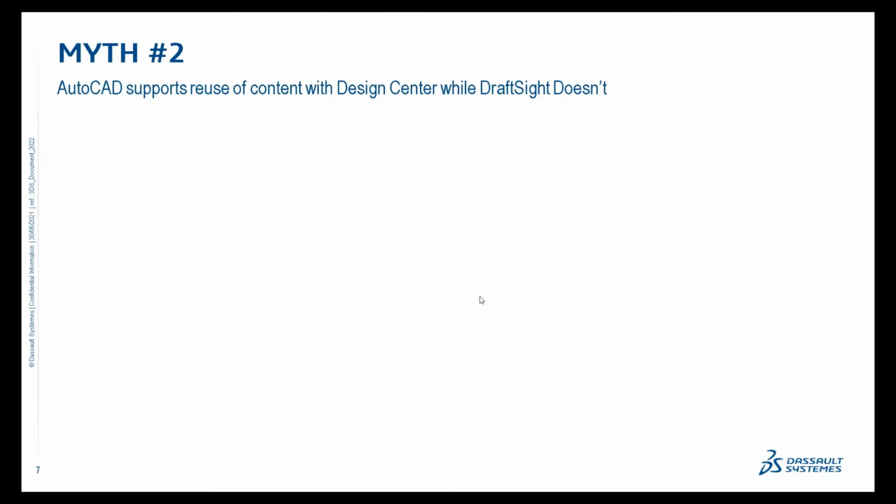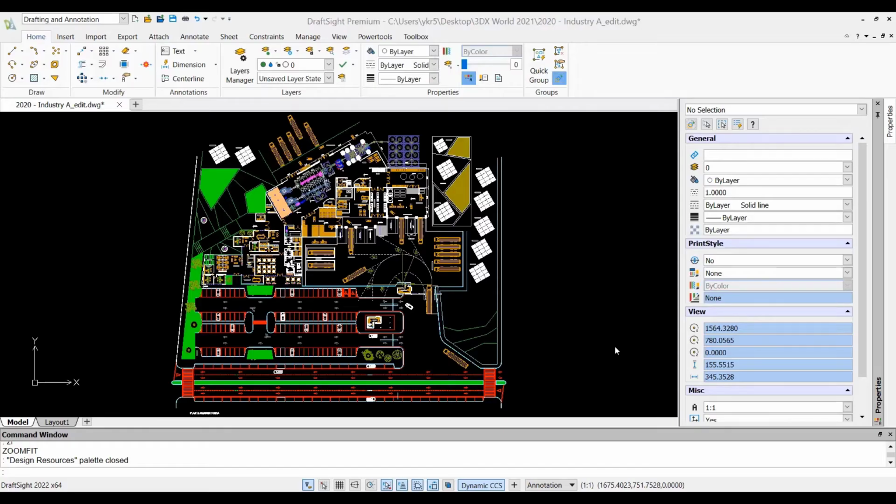Many people I speak with have not used or forget the power behind design resources. So, design resource can be used to capture objects from template and drawing files and quickly drag them into the current drawing file. And why is it important? There might be situations where designers want to share design elements within their own drawings, as well as between colleagues and external consultants. Design Resource Palette helps you browse for content in your projects.